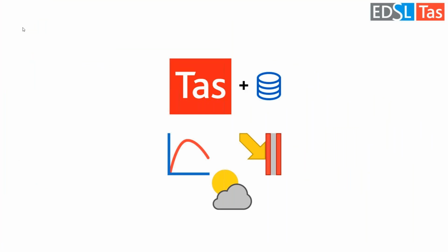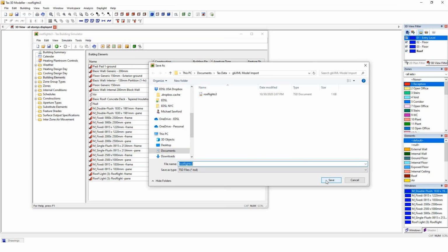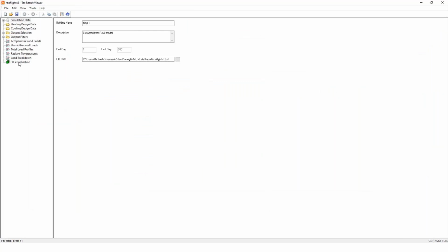At this point, you would add more data: occupants, equipment, lighting, gain profiles, material and construction definitions to the surfaces, maybe weather data, maybe aperture functions for natural ventilation analysis, etc. So you have, in the end, a complete model ready to simulate. If we go ahead and simulate this completed BEM model from the gbXML import, this is just to show that we can complete that middle step in that workflow.